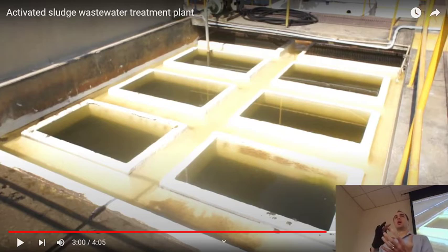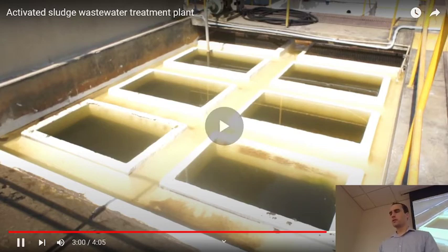So I think that there's probably going to be a little bit of denitrification happening in the typical waste-activated sludge like we're showing here, but more likely, if you need a lot of that happening, you probably design a tertiary step specifically to cause the conditions to be ready for that. Now, I'd have to go back and look at specifically the steps that you need or the requirements. I think some denitrification will be happening in an activated sludge system.